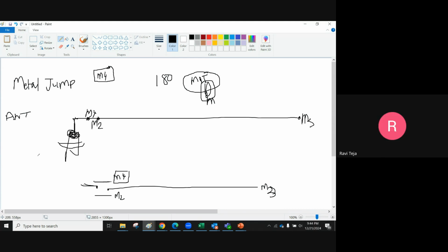That means this is at the time of manufacturing, once the fabrication is done. While we deliver the layout, we think this layout is good and we have delivered. But at the time of fabrication, the gate is gone. In reality, this transistor will not work and the chip is a failed chip. So this is what the antenna effect is. That means the gate oxide is damaged.